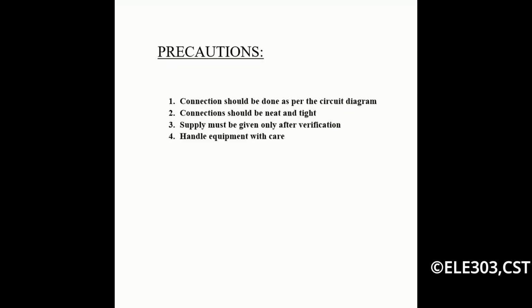These are a few precautions that we need to keep in mind while performing the practical. Number 1. Connections should be done as per the circuit diagram. Number 2. Connections should be neat and tight. Number 3. Supply must be given only after verification. Number 4. Handle equipment with care.